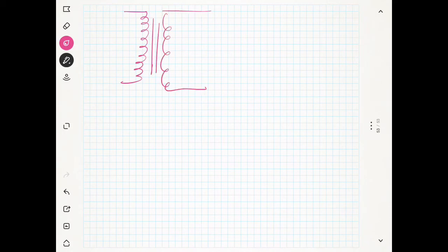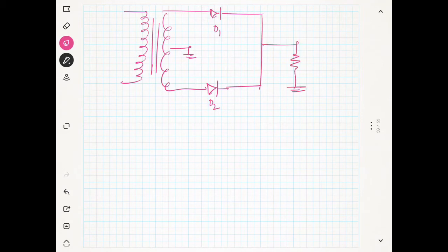So we have got one equation. I will derive the equations now. You have the full wave rectifier with two diodes, D1 and D2, and you have something like RL. Okay, this is your RL, and you will take your output like this, V out. Okay, this is your output. So you are giving V primary, which may be an RMS. Sometimes I will give you peak also. So you can find Vp primary,